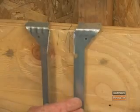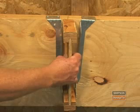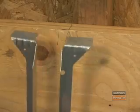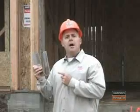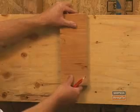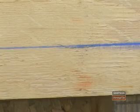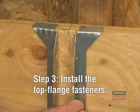You position a top flange hanger differently than you position a face mount hanger. Because of the top flanges, you don't have to measure the height of the joist when installing a top flange hanger. You place the hangers so that the top flanges rest on top of the header. You have to determine the height of the joist to correctly position the face mount hanger. You can determine the joist height by using a small end cut of the joist or a wood block, snapping a location line, or measuring. When you have a top flange hanger in position, you are ready for step 3.